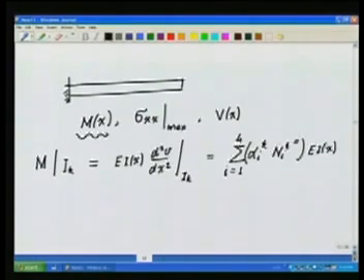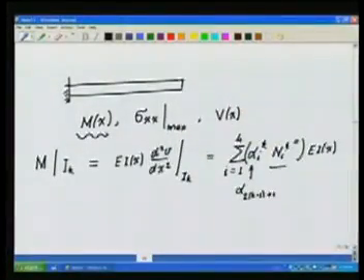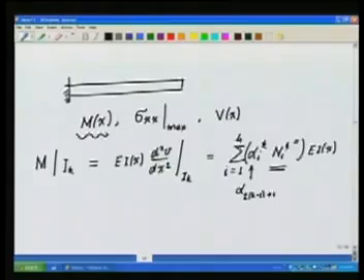So, I know what this alpha ik corresponds to from the global to local enumeration. So, I find this value, okay, this is alpha 2k minus 1 plus I, find the value of this degree of freedom, multiply it with the second derivative of the shape function that we have, obtain the value of the material properties, the flexural rigidity at the given point x, okay. This way, I can find the value of the bending moment at any point in the element. So, by interpolation I can find.